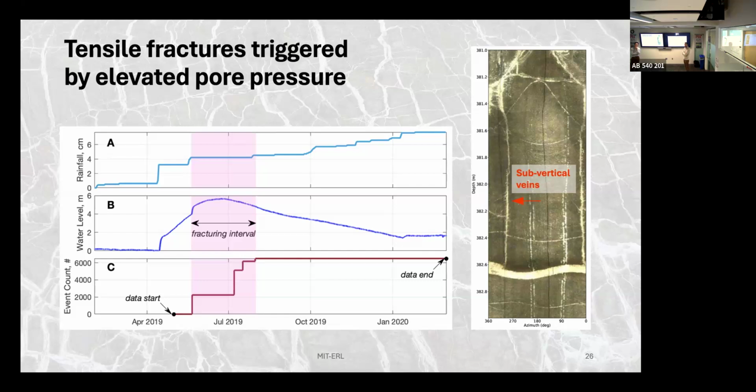So maybe you can test against the acoustic. Does it need to be put in the borehole for a long time? Well, not all the time, but you have to put it down and let it stay a bit, and then it can measure the pore pressure. It's used in open pit mines for early warning of slope failure. Yeah, I don't remember seeing those results, and certainly they were not there for a long time.